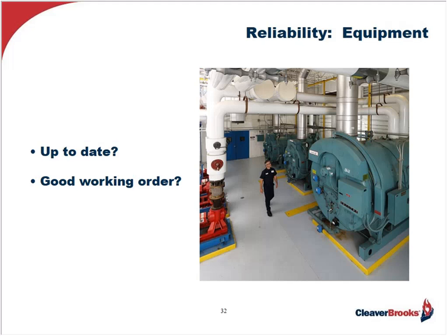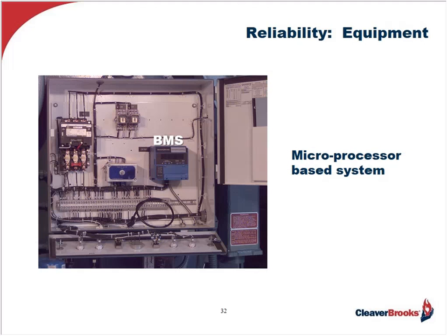Here we're looking for obvious signs on the burner which tell the experienced eye if the equipment is in good shape and up to date with the combustion control system and also with the burner management system, which controls all the burner sequencing and monitors the burner's safeties. It's also known as the programmer. What is especially important is the age of the burner management system or programmer, and if it includes all the lockout information in a clear and readily understandable way, and if it has the capacity to log and store fault history.